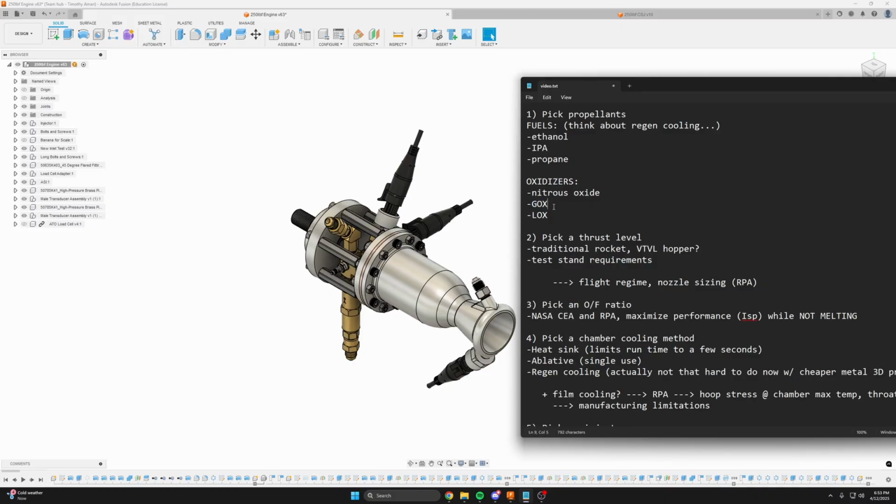If you go to any sort of flight vehicle, though, the low density is really going to hurt you. You're going to need some crazy big tanks, or super high pressure tanks, to store any amount of gaseous oxygen. But it is doable, just not at very high mass flow rates. Liquid oxygen is another one. But you're taking that step into cryogenics, and all your valves and everything need to be rated for cryogenic use. So that has its own set of difficulties. But if you're willing to take that step, LOX is just the best oxidizer.